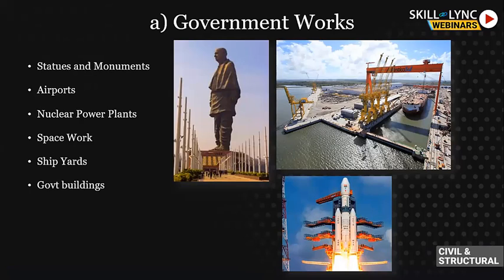Government also works in airports. Airports are very similar to the commercial retail and mall work that we spoke about. Every part of it is different, with huge spans. The challenges are similar to those in the commercial retail sector. The nuclear power plants are very interesting. As I said, the concrete that is used for nuclear power plants is very different, because it also needs to act as a protection against the radioactive emissions of the work that is going on. And also the structure needs to have a huge life. So sometimes it's designed for a 500-year life of the structure.